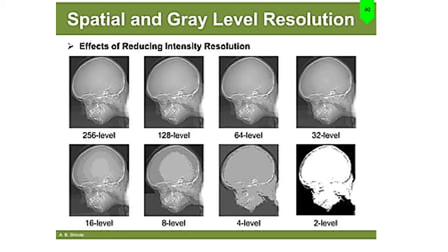Similarly, if we have 256 levels, it has more quality, and if it has only 2 levels, you see only 2 levels. That means 2 colors are used to represent the image. One is black and the other is white. So all the intensity values in the image will be clubbed either to white or to black. But if it has 256 levels, then you have 8 bits of intensity, so starting from black to white, we have many different gray shades also.